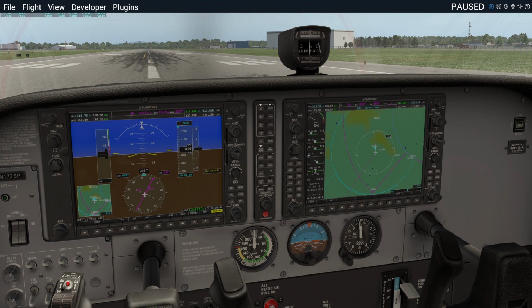The attitude indicator shows pitch up, pitch down, and bank angle. It has a horizontal line across the screen, with the brown being the ground and the blue being the sky, and the yellow triangle and the yellow bars would be like the little miniature airplane. It also incorporates the slip indicator